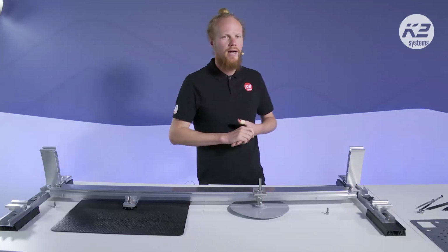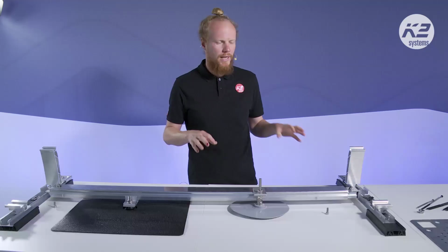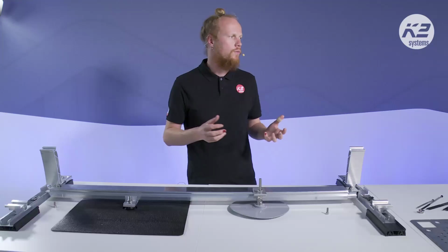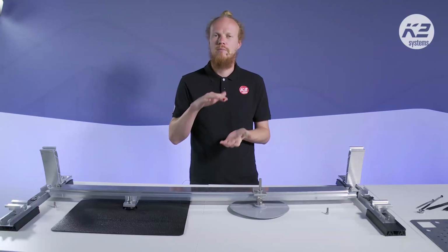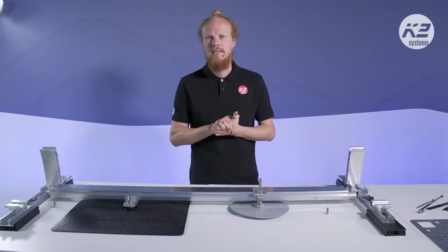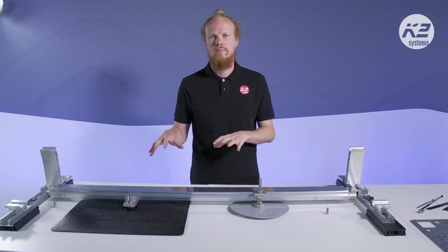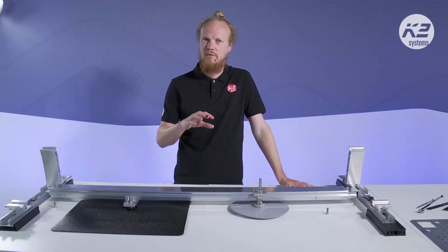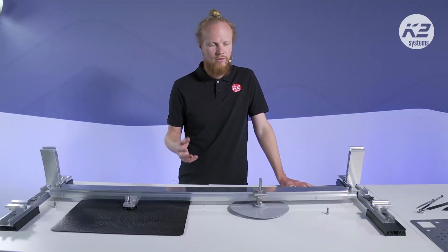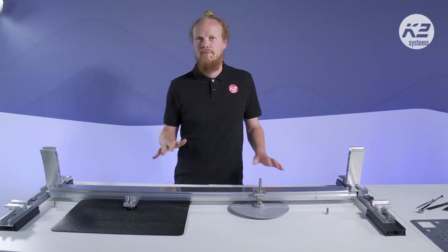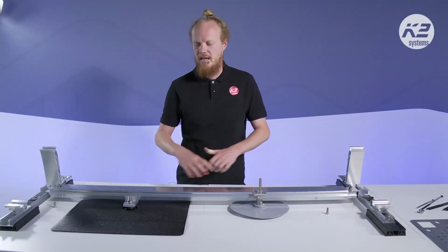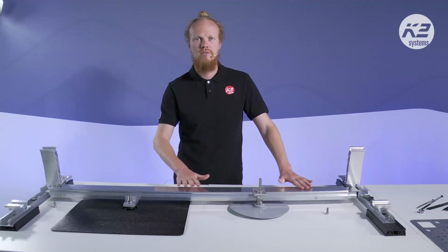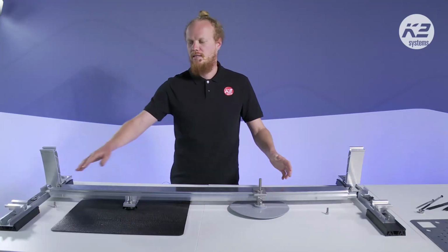Excuse me. We had another question about mineral insulation, and we have two topics that come from that. One is the compression. Often it's quite soft, and there is a concern that if you put too much weight on top of it, it will compress over time. There's usually a 2% and a 10% compression factor that is specified by the roofing manufacturers. With the compression part of things, anchors don't come into it as such. The anchors are usually screwed into what is underneath the insulation, and they are resisting sideways movement and uplift. With the compression, it's actually the downward force.